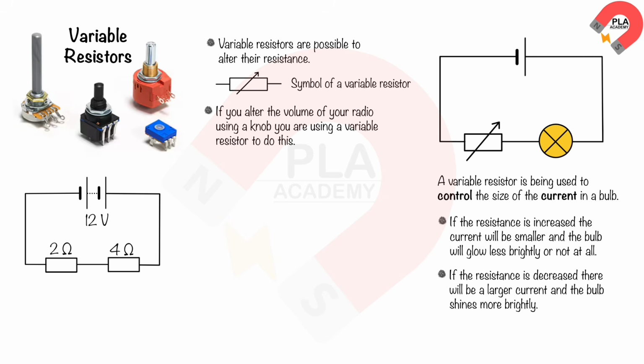The circuit contains a 12V battery, and 2 resistors connected in series. Calculate the current in each of the resistors. Their total resistance is found by simply adding the individual resistances together. This is not true for parallel circuits. You do not need to know how to do this. So, the total resistance the current must pass through is 2 ohms plus 4 ohms equals 6 ohms.